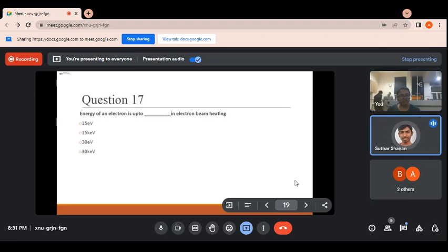The background is a bright field mask, because we are covering only the region where we want to create the structure, similar to the interdigitated electrode. Only that region we are covering, and the remaining area we are not exposing, right? So basically in a bright field mask, only the regions where we need the structure will be covered.